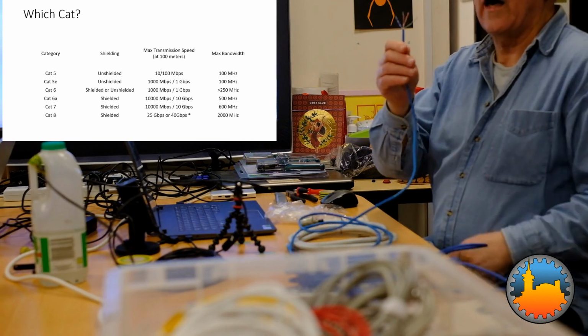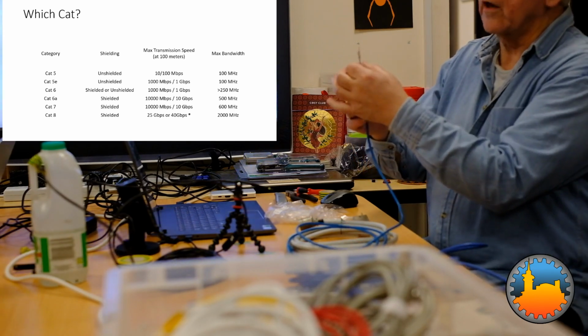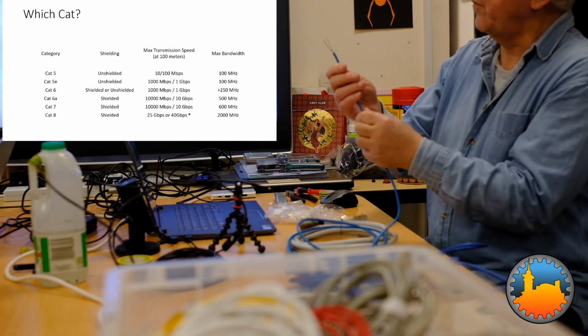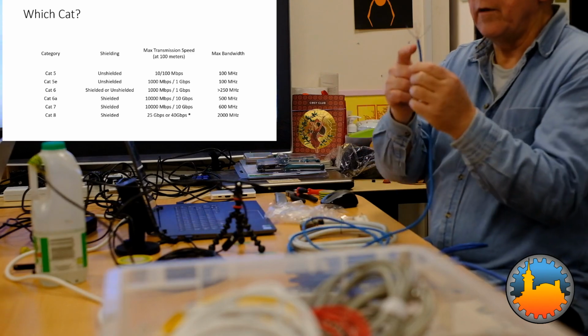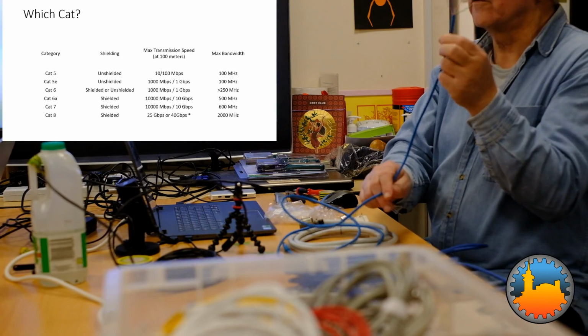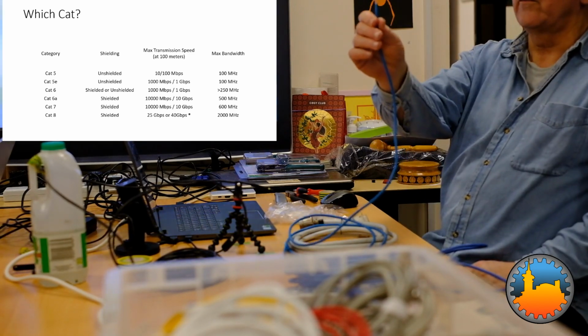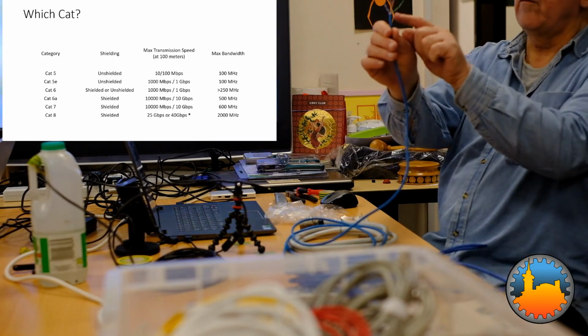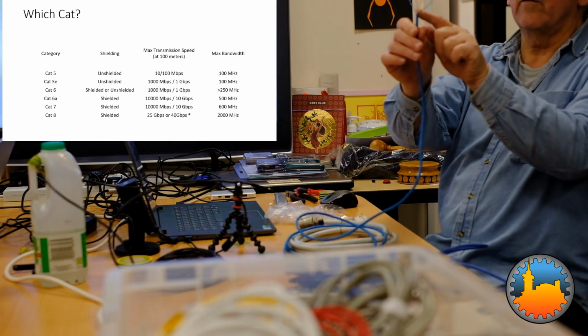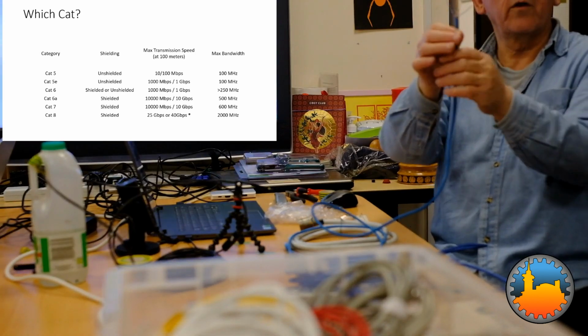But it's very clever stuff, this. I'm always amazed at how this works, because you've really got different signals travelling along these different twisted pairs, and the only thing that stops them getting all messed up with each other on this wire is the fact that they're just twisted at different rates. And you can see there, the brown one is not quite as twisted as the orange one, and the green one is not quite as twisted as the blue one.